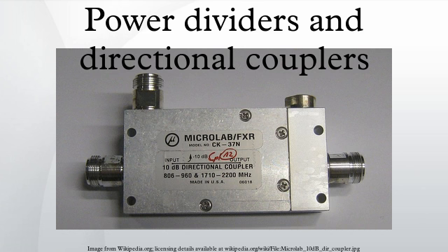Making use of isolation. If isolation is high, directional couplers are good for combining signals to feed a single line to a receiver for two-tone receiver tests. In Figure 20, one signal enters port P3 and one enters port P2, while both exit port P1. The signal from port P3 to port P1 will experience 10 dB of loss, and the signal from port P2 to port P1 will have 0.5 dB loss. The internal load on the isolated port will dissipate the signal losses from port P3 and port P2.